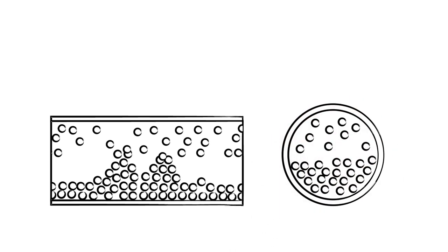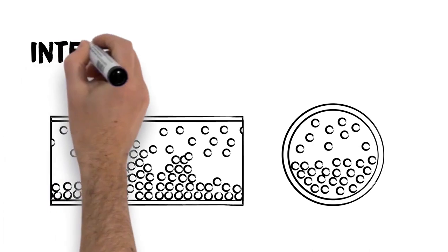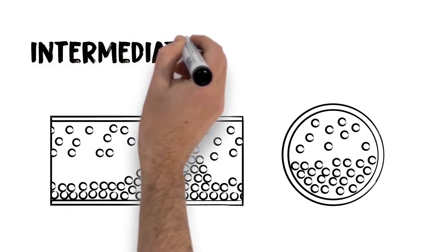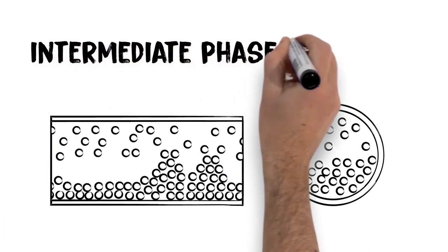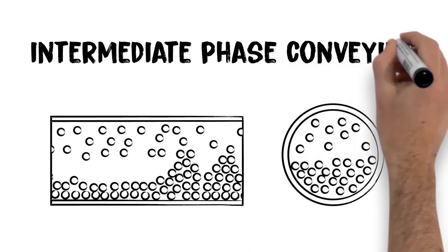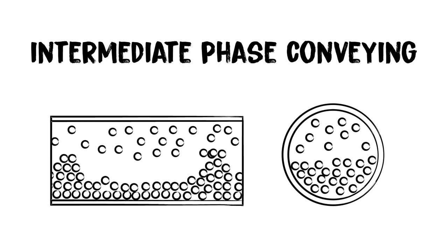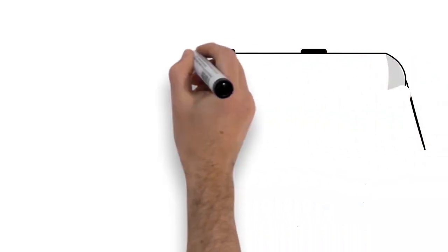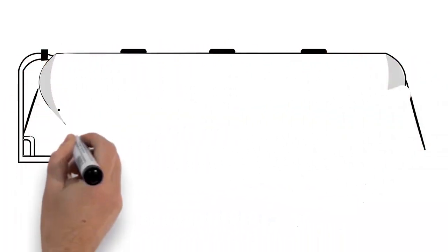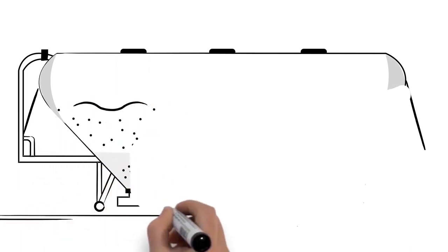Because the open area of the pipe is reduced, the air velocity increases, causing the air to pick up more material. Conditions then become unstable, but the flow becomes self-regulating and plugging is unlikely to occur. Material characteristics are not the only factors important to efficient pneumatic conveying.